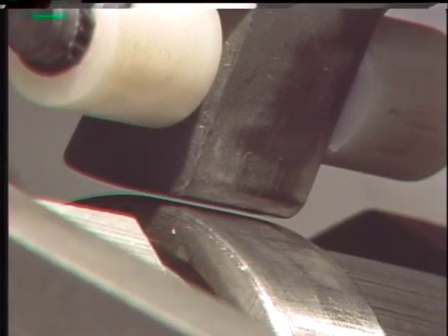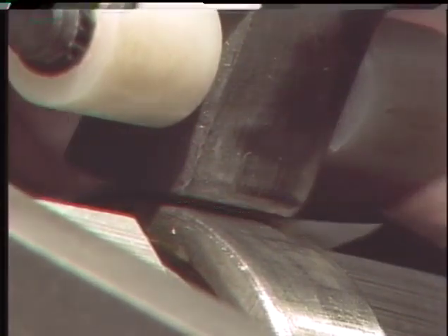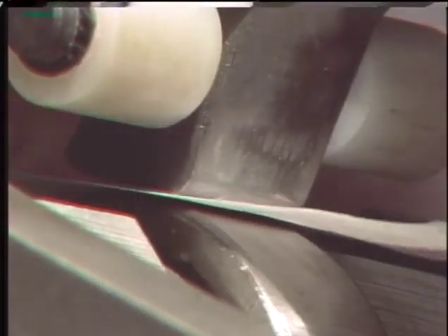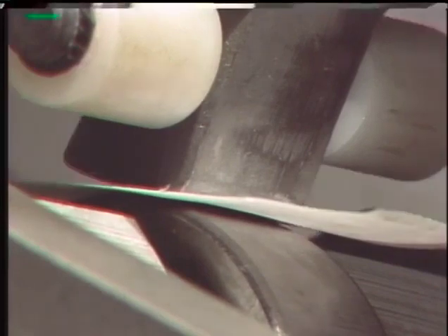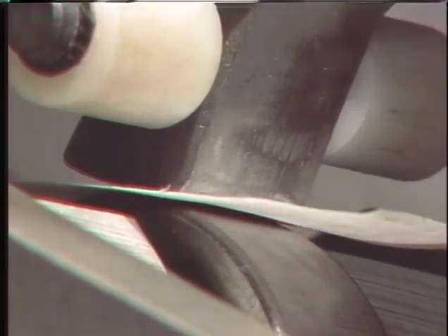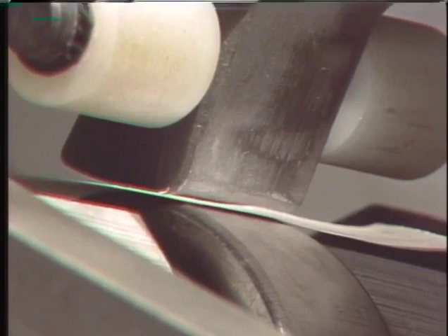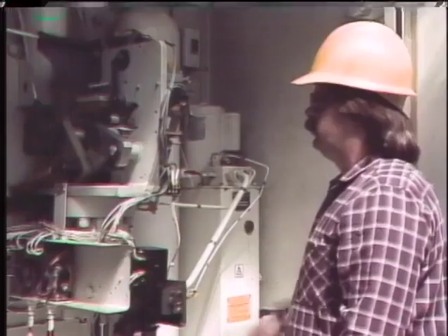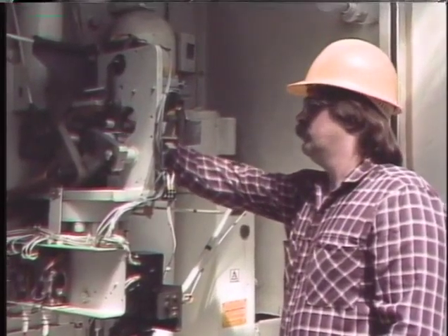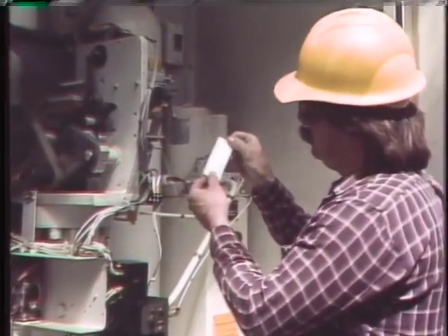Another way to check latch wipe is to insert a piece of paper between the latch and the roller surface that it normally holds. Slowly crank the mechanism into position so that the roller presses against the latch. When the mechanism is released, the impression left on the paper represents the latch wipe, which is compared with manufacturer specifications.